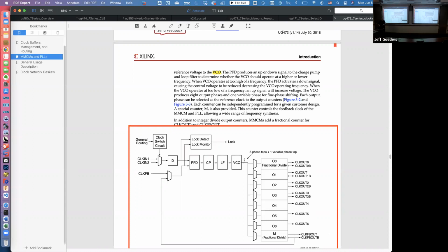Okay. But you don't write behavioral SystemVerilog and have one of these pop out. You have to read the documentation and learn how to instantiate one of these clock guys. It's an advanced topic, but if you're going to do high performance, important design, it's one of the things you have to learn. But of course, to make it easy, what does Xilinx provide? A clock wizard, where you say, my input is this frequency, I want these output frequencies, and here's what I want for the phases. And it does all the magic and outputs the instantiation for you.